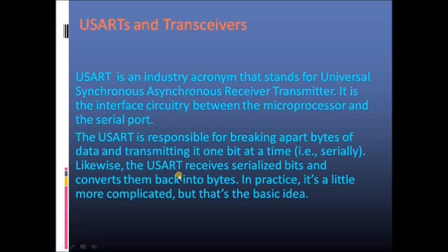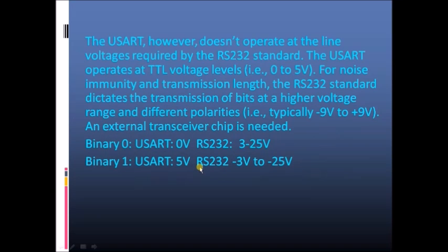So we need to convert that parallel data into serial form, and then give that serial information to the peripherals. In the same way, if serial peripherals transmit serial data, the processor understands only parallel data, so there we again need a serial to parallel converter. So parallel to serial and serial to parallel conversion is done by this USART.